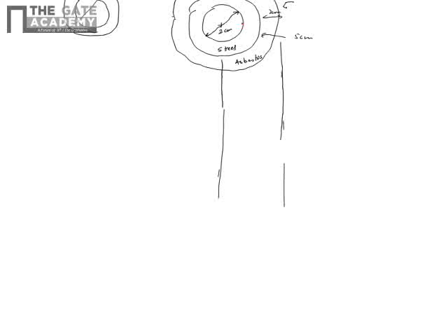So you have the material here and here, so it's better to draw a resistance network. The resistance R1 of the steel and R2 of the asbestos. Now in radial heat transfer, the resistance is given by ln(outer radius by inner radius) divided by 2 pi L K. They are in series, and the heat transfer per unit length is asked, with the temperature difference between the innermost and the outermost surfaces.